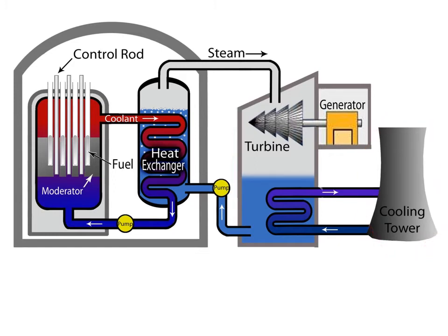The warm water leaving the condenser is carried to the top of the cooling tower. The water is sprayed out at the top of the tower as droplets to increase surface area. This increases cooling ability. As they fall, the water cools. It is then sent back into the system to help further condense more steam.